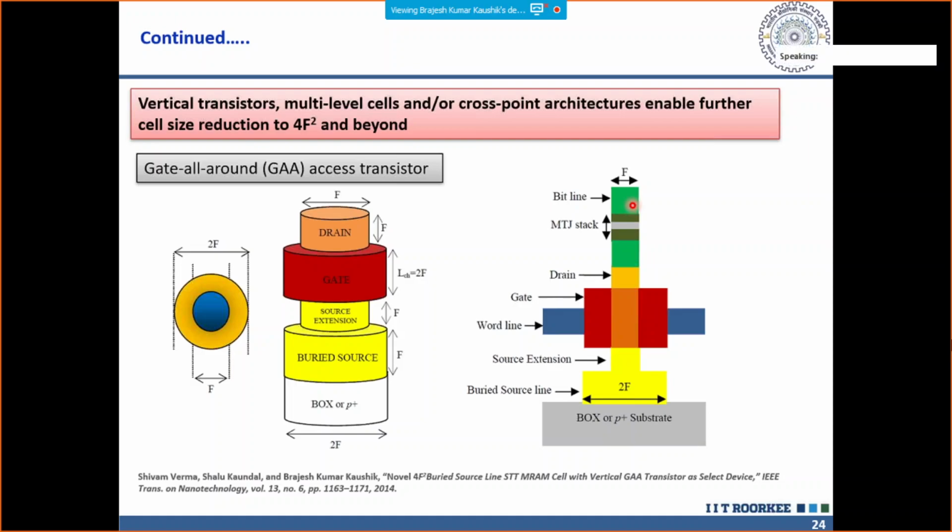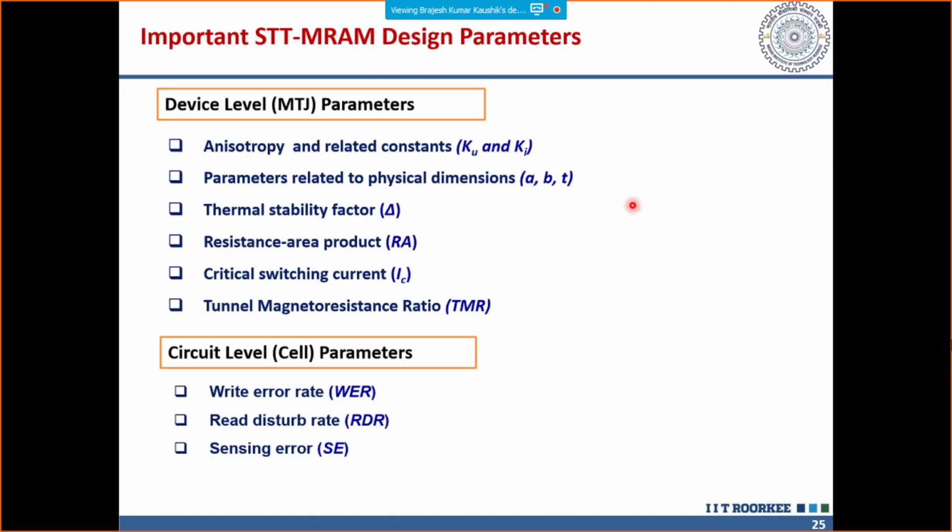Instead of using a planar transistor, if you're using this GAA, we are able to reduce the overall area by 33%. And that is where you gain maximum out of it. While we were reducing the area, the overall performance did not change at all. In fact, we had a better performance in comparison to the planar based transistors.